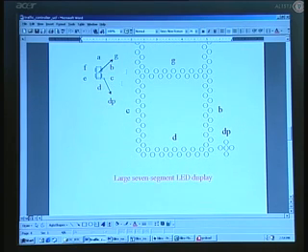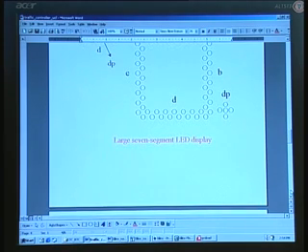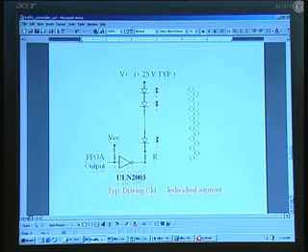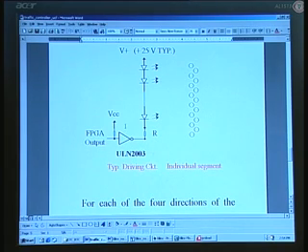And the flexibility that you have is you can make it any other size you want. All you have to do is add more LEDs, and the interface circuit that you need will be as shown here. So, for example, you have what is called a ULN 2003. This is a device available. It is actually a Darlington pair, and input is coming from the FPGA output. Say one of the lights that you have already seen, main, red, etc. They are all single bit outputs. They are all connected here, and this is just a typical representative circuit for one of the traffic lights.